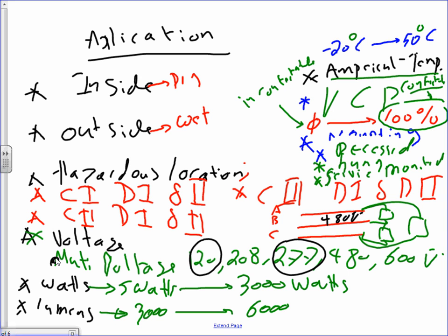The second thing I want to talk about, guys, is the ambient temperature. Fixtures, most fixtures in Minnesota, we appreciate that one. Most fixtures are rated to operate at -20 all the way to +50, and these are Celsius, right? These are hot and very cold, right? But there are good applications for both of them. For example, fluorescent is not a good application in Minnesota. We get cold. It's not efficient to put it outside, right? High intensity discharge is a great application for outdoor in Minnesota. But typically they are rated between these two, -20 all the way to 50 Celsius, ambient temperature. That's where we give you the convenience.